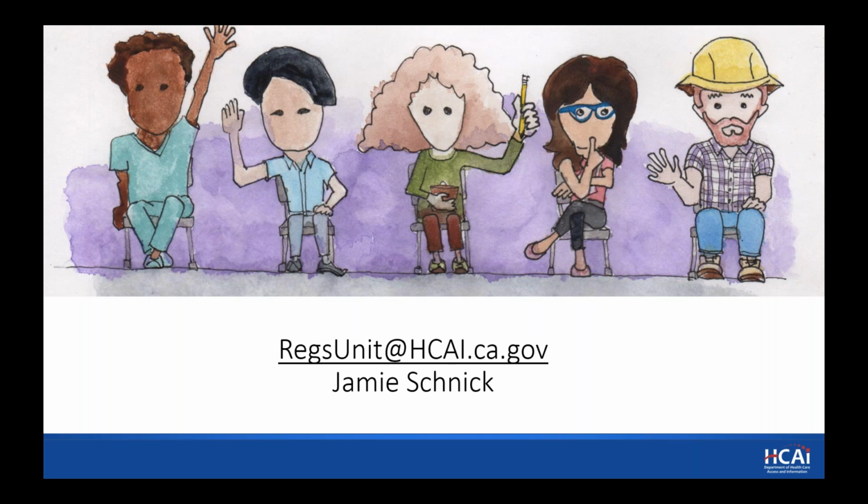For it to be accessible, I hope we could all be in agreement that the GFCI receptacles have a label saying they should be tested monthly. The idea is that you're protecting the public from a ground fault. To be readily accessible, it could be at the breaker.